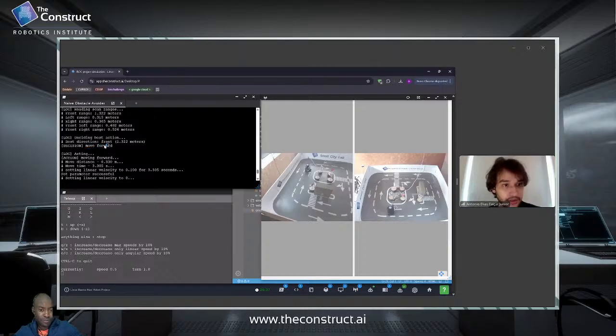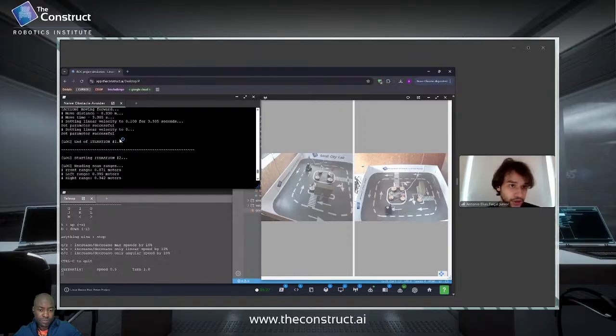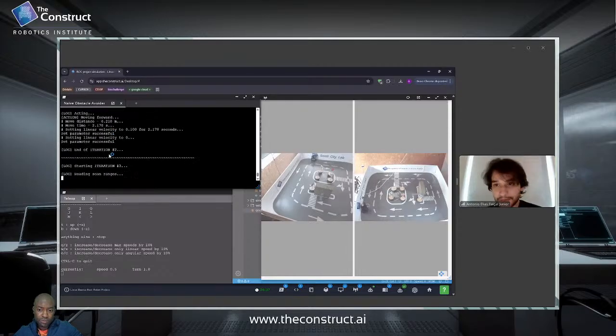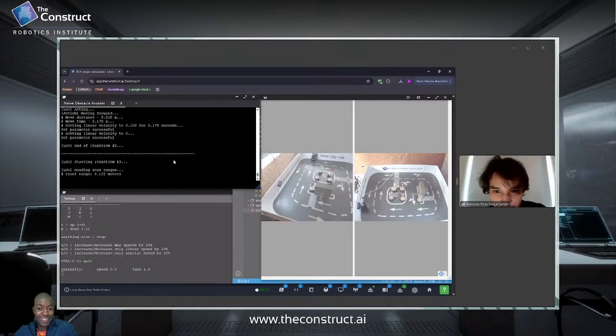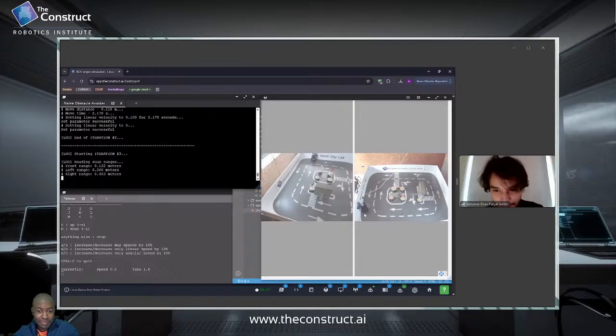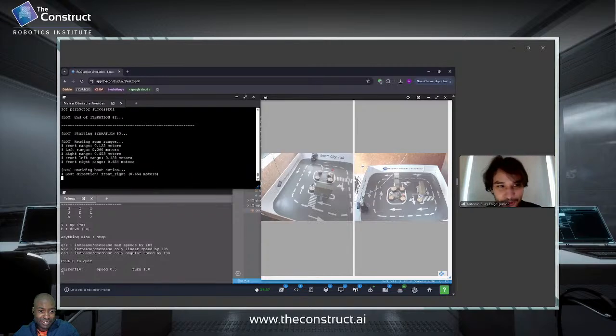That decision is then fed to an action function, which calculates what it has to do. If it has to move forward, it calculates how much and for how long. And if it has to turn, it then turns. Right now we see that it did not turn. So what's going on? What do you think might be going on there? You mean because it crashed? I don't think it actually has crashed. It just got extremely close to the right wall.